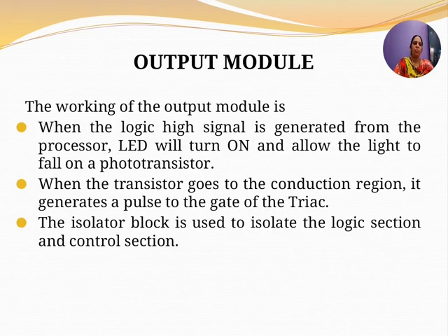The working of the output module is, when the logic high signal is generated from the processor, the LED, the light emitting diode, will turn on and allow the light to fall on the phototransistor. When the transistor goes to conduction region, it generates a pulse to the gate of the triac.